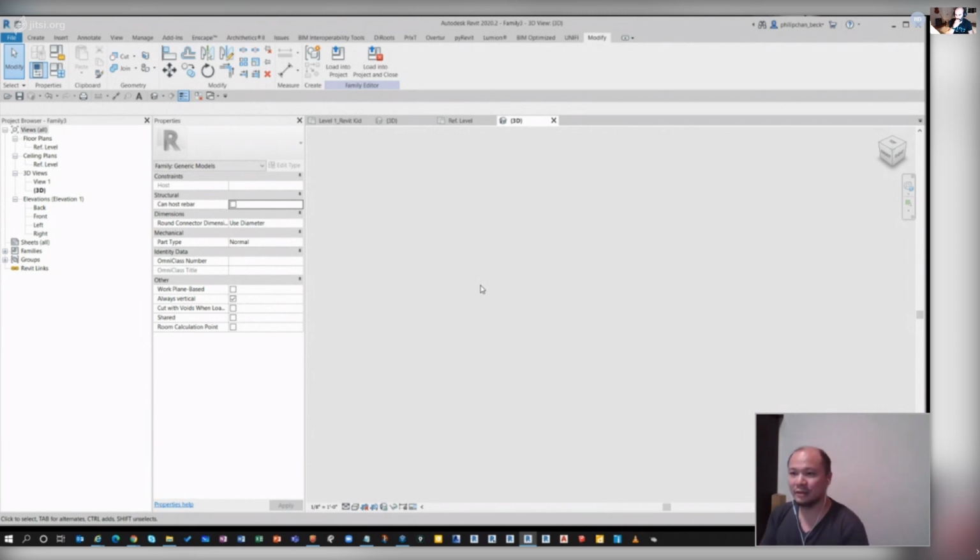The technique that you can apply, you can use it on anything that is a sweep or, again, swept blend. You can't use it on extrusion, nothing for revolve, or nothing for blend. You just can't use this technique on other things. Only sweep and swept blend. Okay, all right. Basically, I'll start a simple geometry in this blank file here.